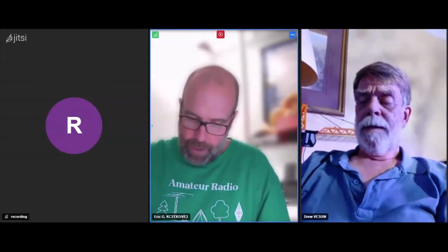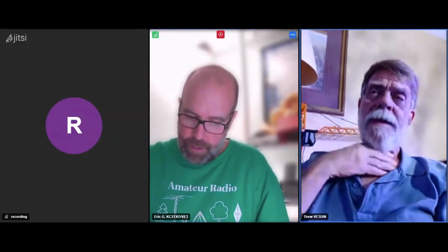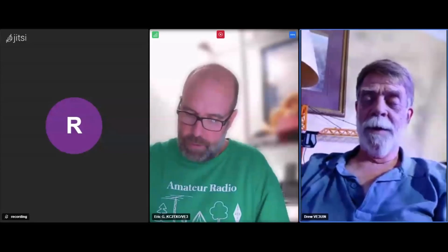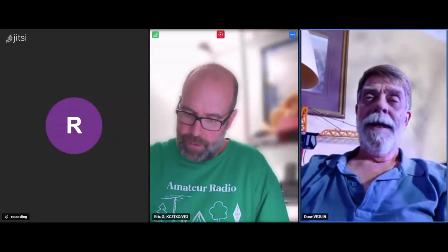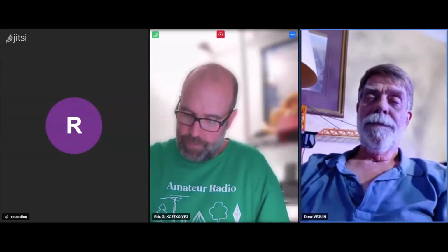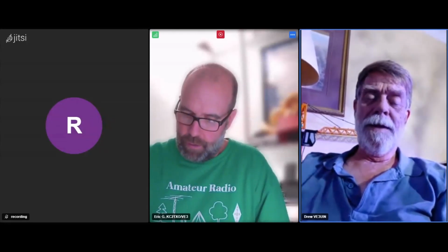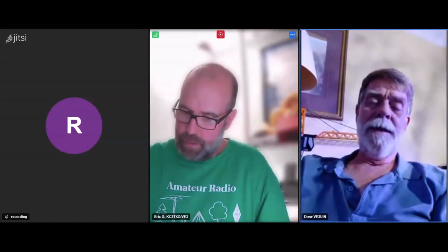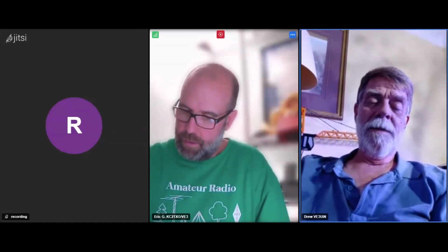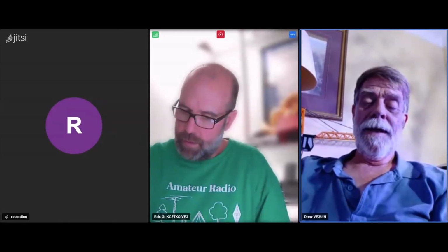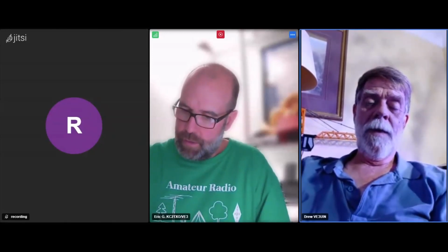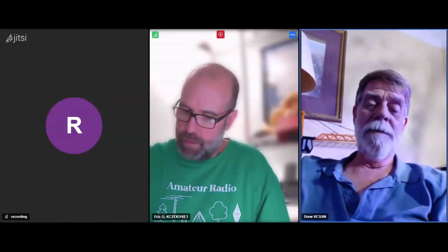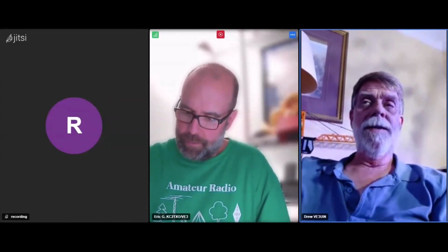When I built my end-fed, I go up on the roof a lot. So I went up there and had my son stand down at the box, and I would just fold back the end of the antenna, and starting from there and using the Nano VNA, figure out whether it's too short or too long, and just keep lengthening it a couple of inches at a time until it matched up. So I matched the antenna to the situation.